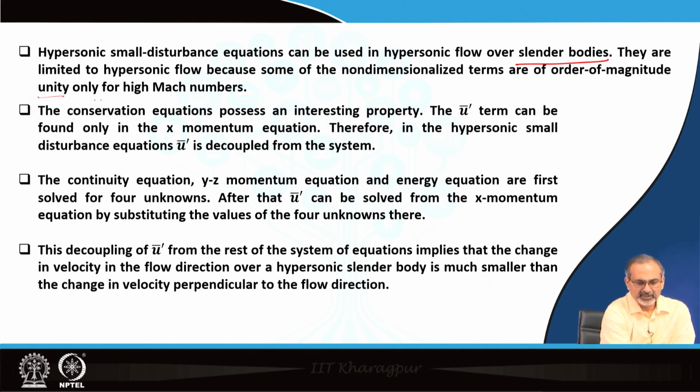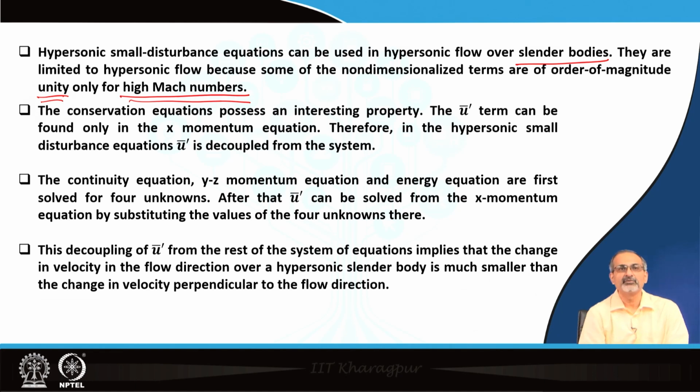So, they would be unity when M infinity is significantly large, not otherwise. Conservation equations possess an interesting property. The u bar dash term can be found only in the x momentum equation. Therefore, the hypersonic small disturbance equation concerning u bar dash is decoupled from the